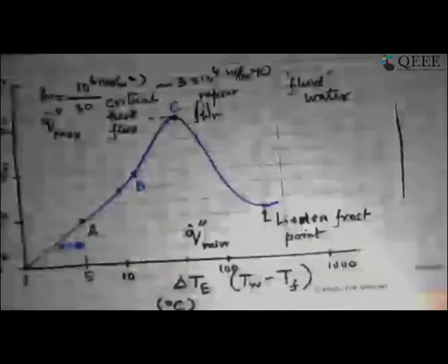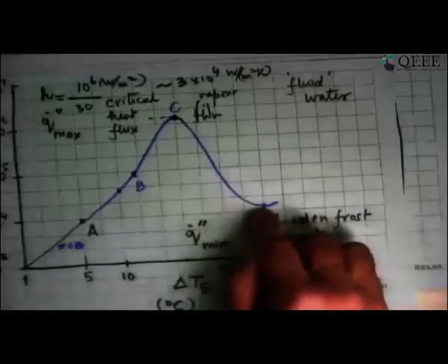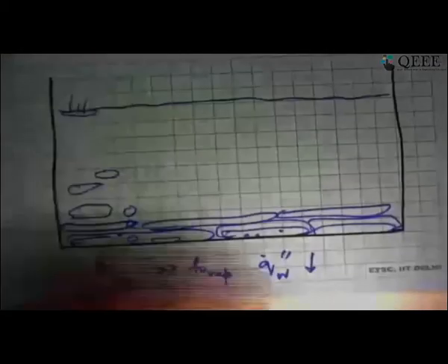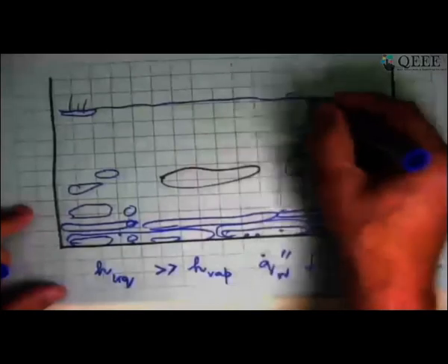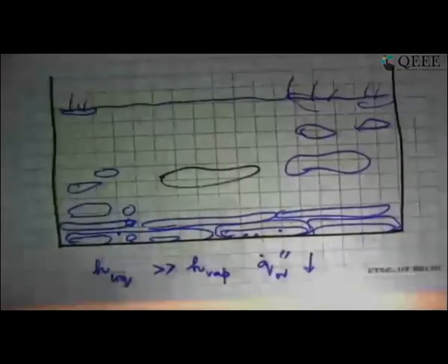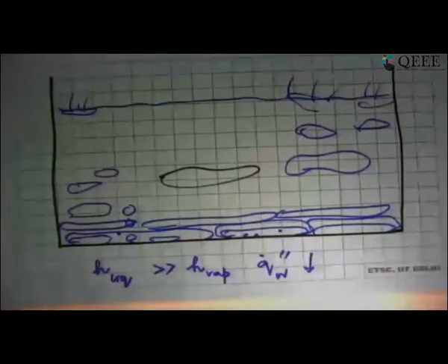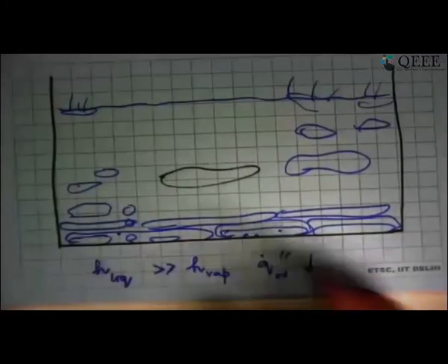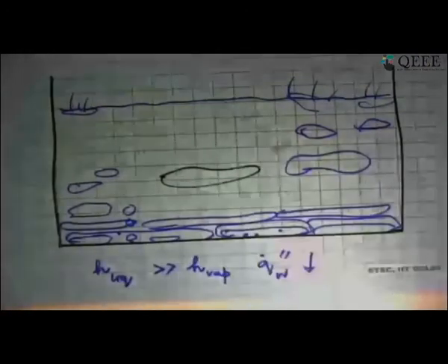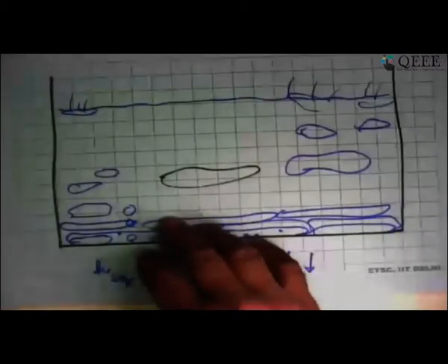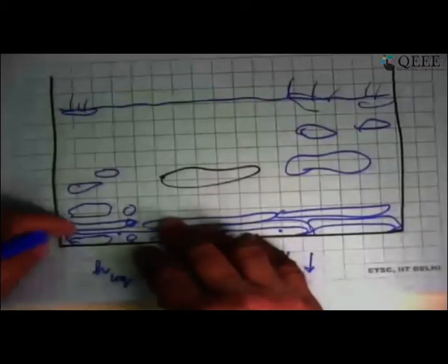So this is one thing that is happening. And in this Leidenfrost point, we have reached a minimum, and the minimum has happened because now the surface is hugely blanketed by vapor. These vapors are now no longer spherical. They are very irregular in shape. They break, they join, they reach the surface, and they start throwing out vapor into the free surface. So that's the reason why we saw that minimum happening, and we said the minimum will happen when this whole thing is very badly blanketed by a film. So that means very few amount of the liquid actually comes in contact with this.